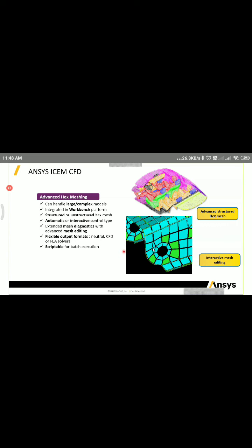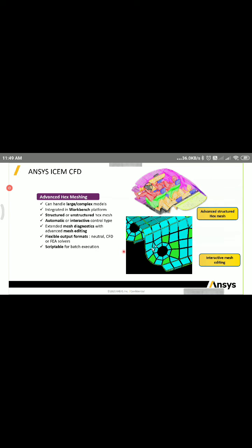Okay, it can be generated with other approaches, like you can have the mesh for hexacore, or you can have the mesh like wrapper, shrink wrap, or you can have the tetra plus prism. So different algorithms are also available. But as discussed, you use this algorithm only in case there is a hexahedral meshing requirement, or else Fluent meshing is good enough to tackle all your CFD problems with the less mesh count with the polyhexcore or polyhedral, right?